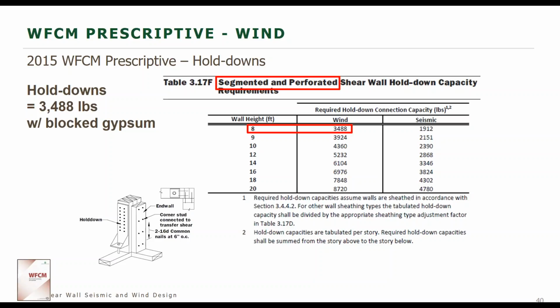Obviously, if you have two different walls, they'll have two different hold down requirements. So you would need to ensure that the shear for whichever wall does not have the hold down directly attached to it, in this case this portion, that detailing needs to accommodate however much shear needs to be transferred to the hold down.